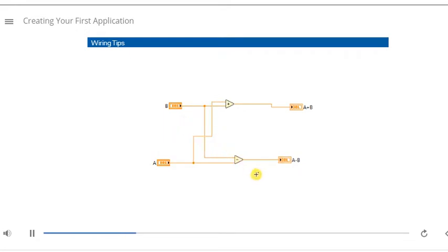When developing a VI, you sometimes end up with broken wires. You can either remove each broken wire by selecting it and pressing Delete, or you can press Ctrl-B to remove all broken wires. Note that using Ctrl-B to remove broken wires removes broken wires that you don't see, as well as those you do see. For example, it will also remove off-screen wires or wires in other event cases.